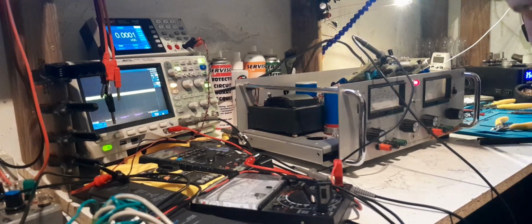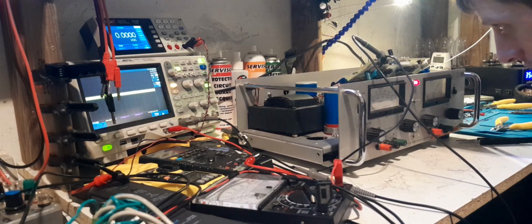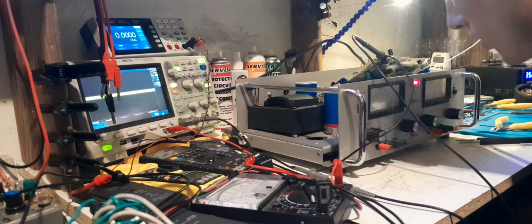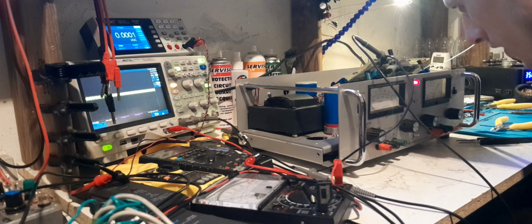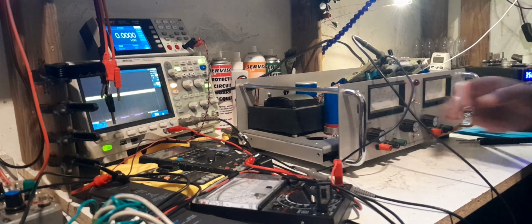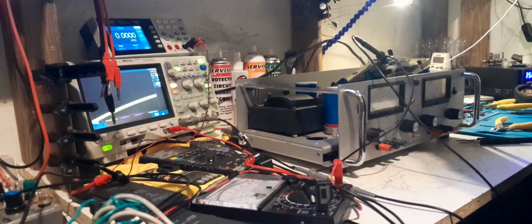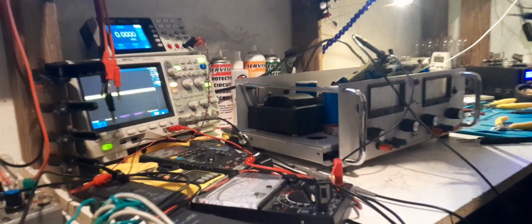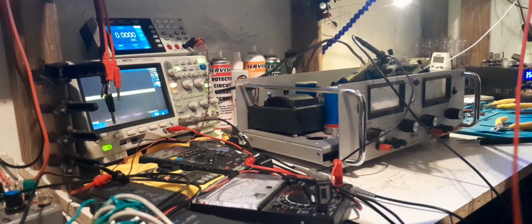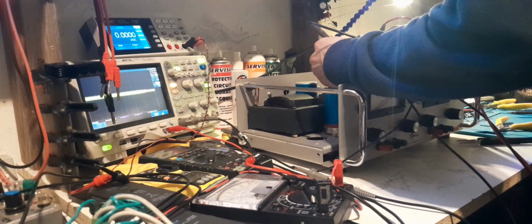And it's all part of the one circuit. There isn't really any active components in it. I mean, there's a 1N4148 diode and a transistor. I'll just quickly test the transistor and see if any of its volt drops have changed radically, indicating that it might have changed characteristics and have a problem.